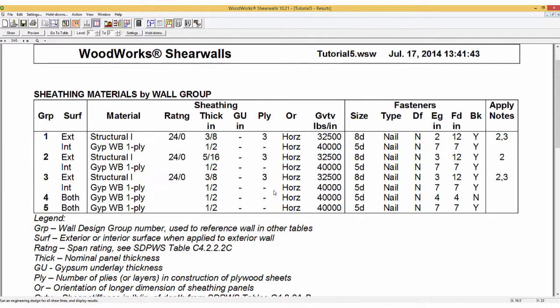A multitude of sheathing combinations or wall groups in the design results is not practical. Therefore, a good strategy is to limit the unknowns in the design in order to reduce the number of wall groups. Furthermore, using the feature of design and group for walls that are expected to have the same configurations will also reduce the different wall groups.